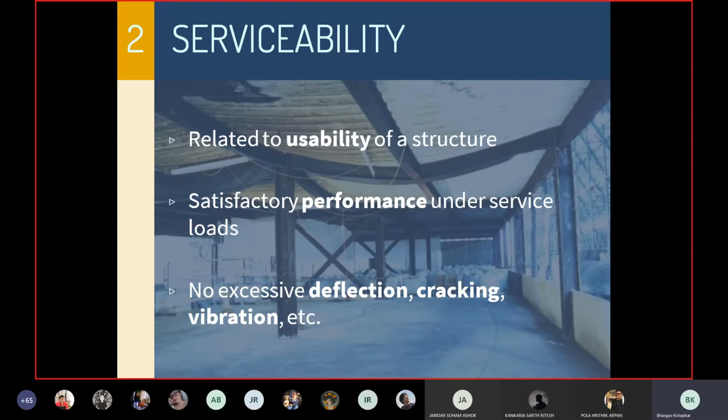So basically every structure or every building has its own frequency. And what happened in this particular case is the frequency of the wind happened to match with the frequency or the time period of the bridge, because of which resonance occurred. And because of this resonance, the structure or the deck started swaying uncontrollably, and after some time it gave up.